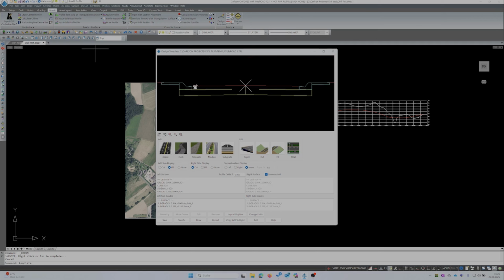In this stage, we've got a top layer with a curb stone left and right. Put a little bit of pedestrian or cycling path next to it, a solid bed as a foundation, and we'll have a bit of a grading next to our pathways, and we've given it an angle for any cut and fill operations that we would need to use.